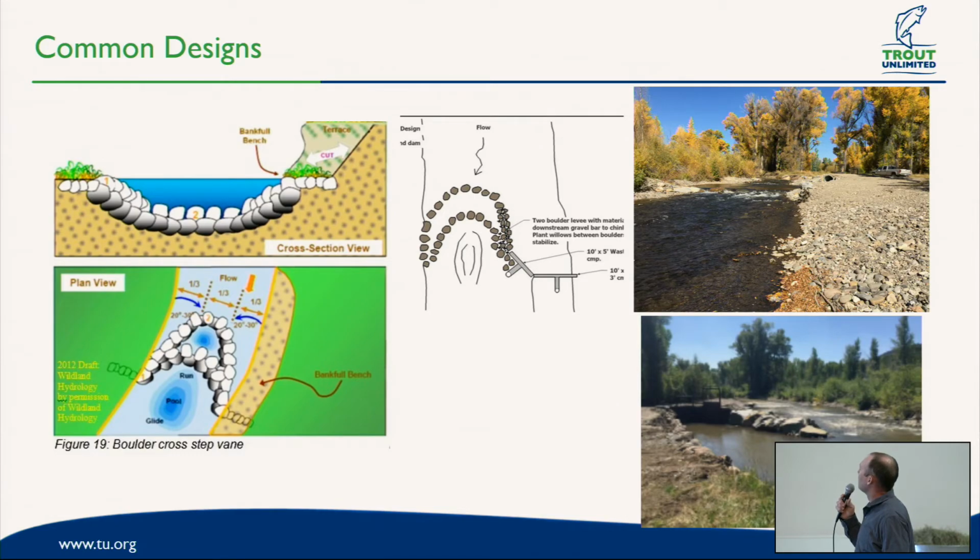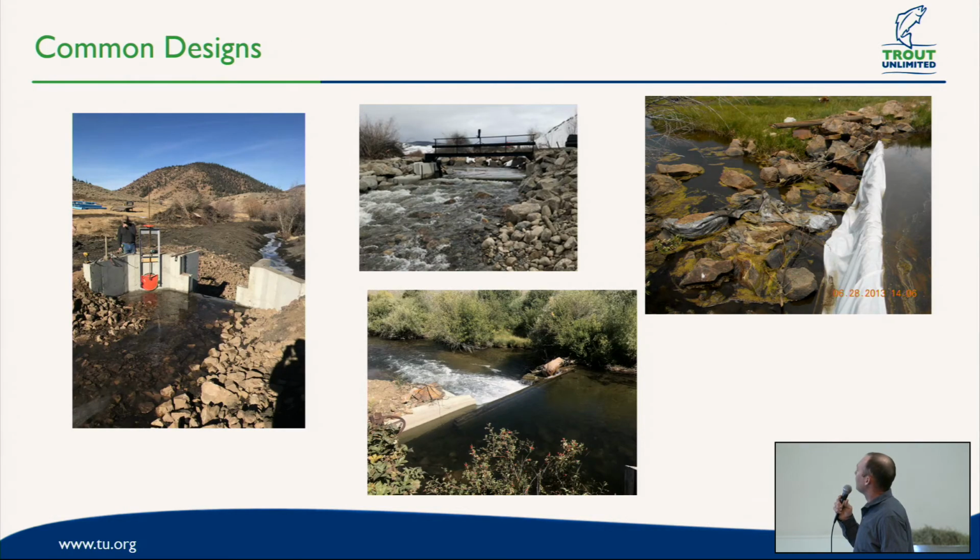I might have skipped over one slide back here that I was going to show you because there's another. Yep, here we go. Just real quick, there's another kind of effective structure, similar to how beavers work, that's often used on Quartz Creek or Tamichi Creek. Here's the stacked logs. You have 2 buttresses, and then you stack logs across. Same in this situation, but during real low flows, you'd use a tarp to seal it up.